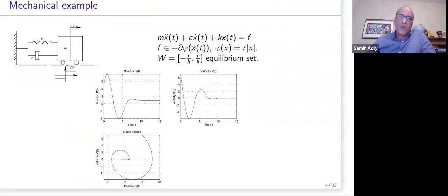It's very famous, but I want to give you this model in order to observe something very interesting, which is the convergence of the trajectory in finite time of the dynamic. We have here a mass. This is a 1 DOF, 1 degree of freedom, mass-spring-damper. We have a mass, a spring and a damper, with damping C and K the stiffness coefficient. And this mass is sliding on the floor, and we can model this contact with simple dry friction, as you see here. It is the simplified Coulomb dry friction, if you like, monotone friction.